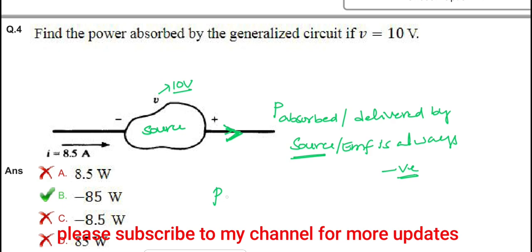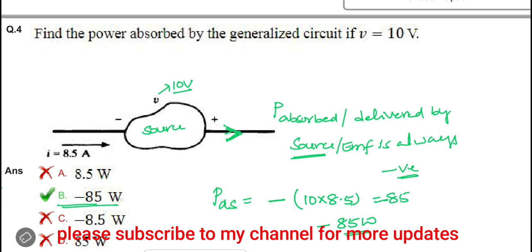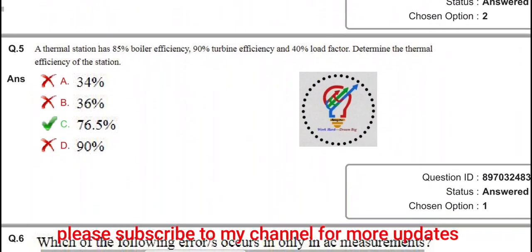So for power delivered or absorbed, the power delivered by the source is equal to minus of the voltage 10 times the current 8.5. So it is 85, and with the minus sign, minus 85 watts. So the answer is B, the right answer for this question. We'll go to the next question here.